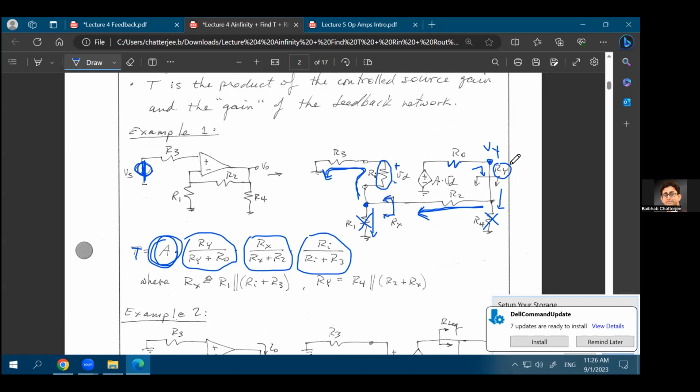No, you are trying to find out the voltage at this point. So let's call it VO. So you're trying to find out VO over VD. Why? Because you want to consider the effect of this output resistance. If you just consider VY over VD, you forget about this R0 resistance, right? Which is not the correct thing to do. You're thinking about all the non-idealities in the op-amp. And RO, this output resistance, is one of the non-idealities in the op-amp. The only way to consider this is to start from this point.